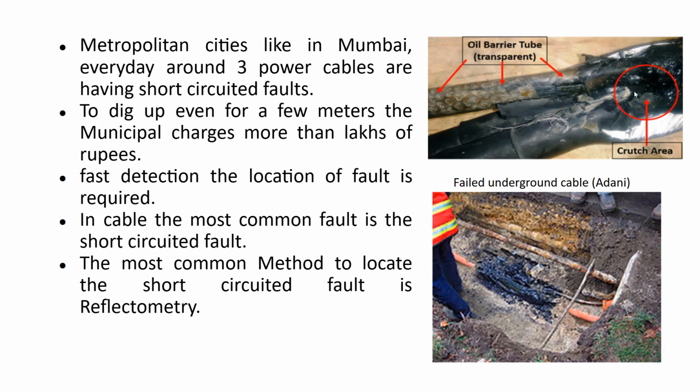To dig up even a few meters, the municipal charges are more than lakhs of rupees, for example in Mumbai city. So fast detection of the location of the fault is required, and accurate detection is also required. In cables, the most common fault is the short circuit fault. The most common method to locate it is the reflectometry technique.